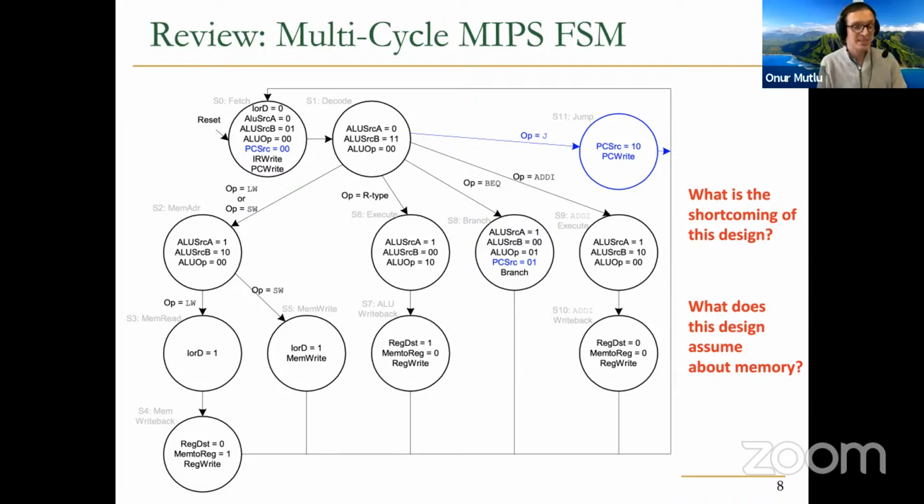And the memory's ready bit that indicates whether or not the data is ready can be the transition trigger to the next state. Clearly, we know how to design finite state machines by now, and you can use a ready bit coming from memory to indicate when you should transition to the next state, right? And if you're really interested in knowing more about this, I mentioned that you should watch some other lectures that I pointed to last time, or read the backup slides that I gave you last time, or read your book, which has more detail. Actually, the book in this case is the Patt and Patel book, which covers multi-cycle memory access. So in this particular lecture, we're still going to assume memory is single cycle in a pipeline processor.